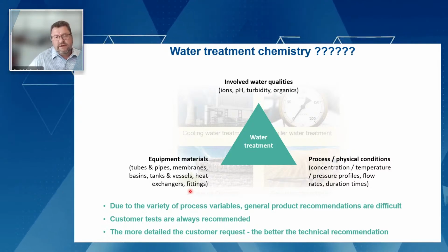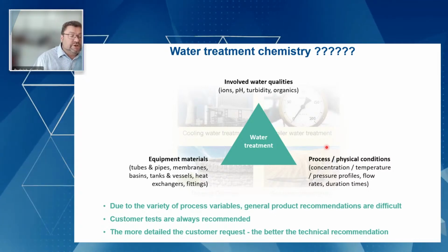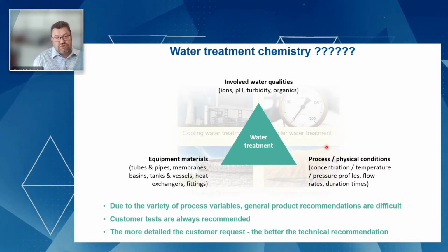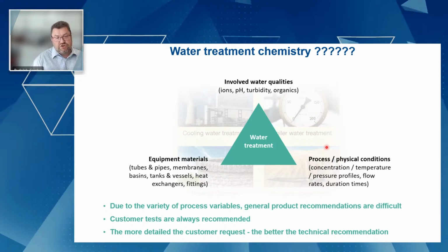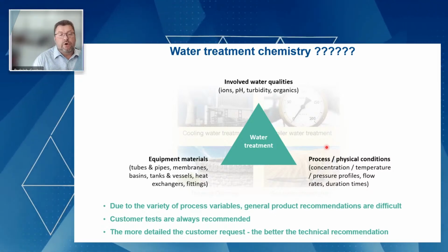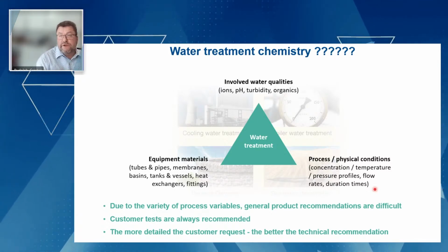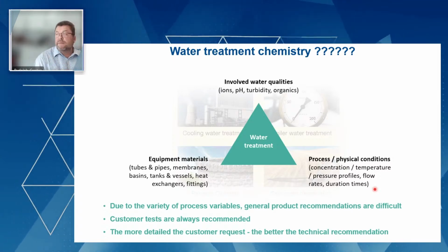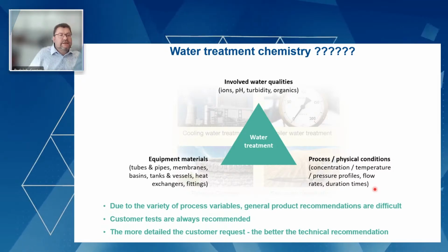This will influence which water treatment service needs to be done. And finally, of course, we have the process or the physical conditions, such as the duration time. Depending on the process we speak about, we could have a very short duration time if we think of reverse osmosis, for example, or a rather long duration time if we speak about cooling towers. So this depends on the process.